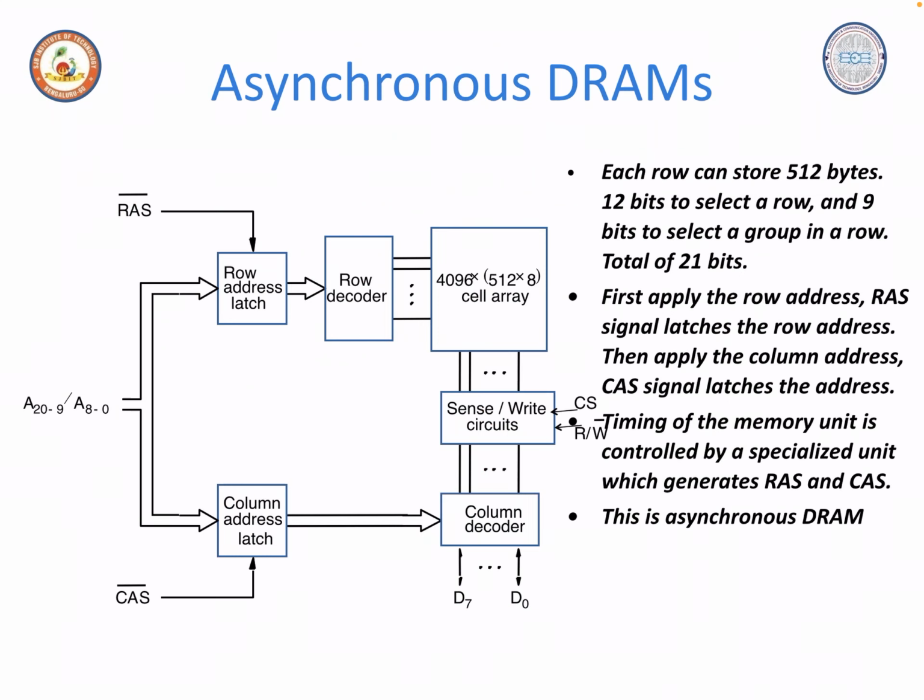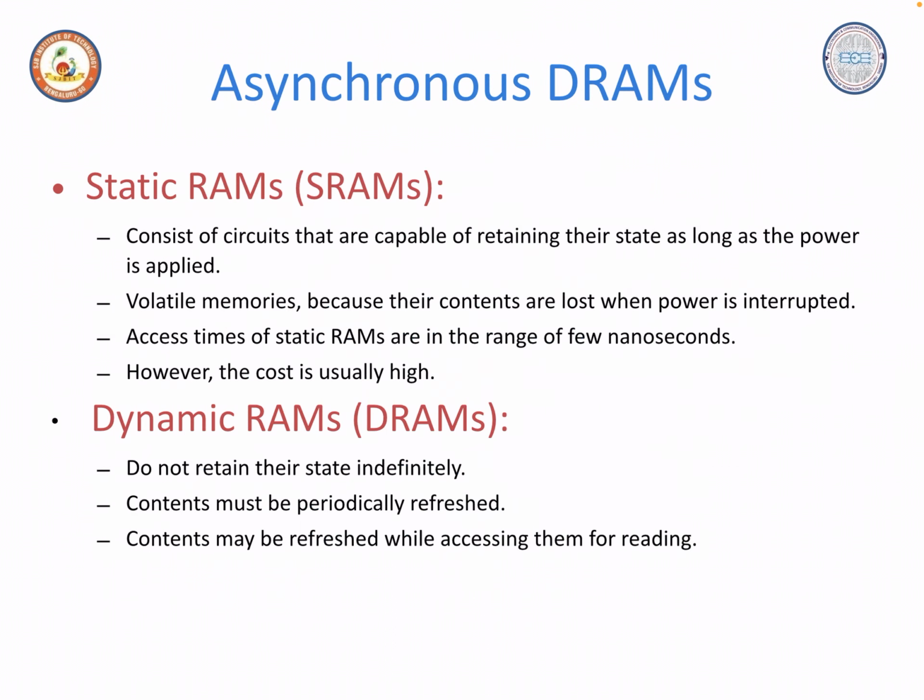So this is a diagram of a single DRAM cell. If you observe, you will have a word line, a bit line, and a single transistor along with a capacitor. Whether the transistor turns on or off is decided by the word line, and once the transistor is active, the data present on the bit line will be charged onto the capacitor.